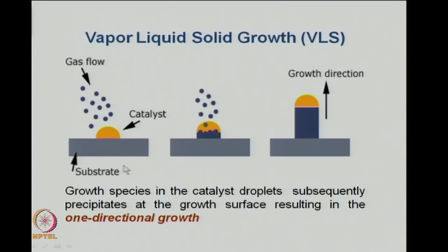So, what happens when you heat this substrate? You have particles of these in the gaseous state. The substrate which you want to make into a nanostructured material, you have it in the form of gaseous molecules. These gaseous molecules then impinge on this liquid droplet, which is the catalyst or the impurity.